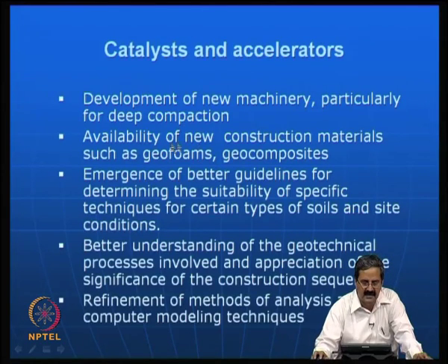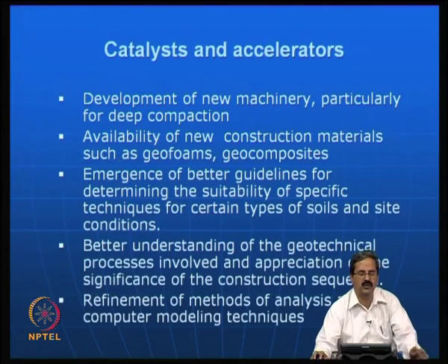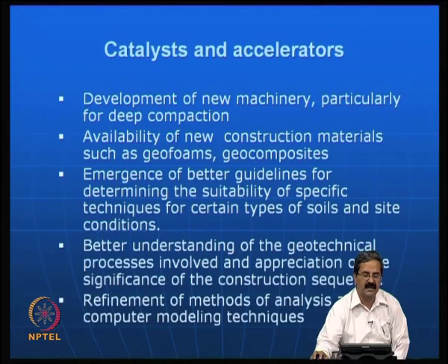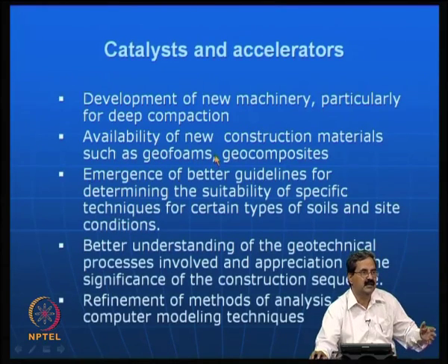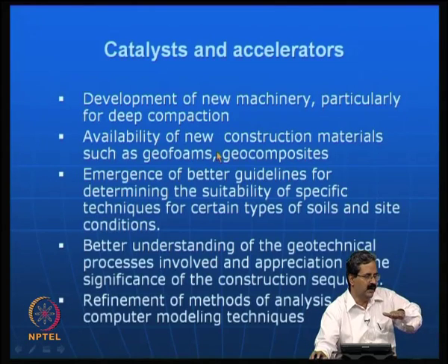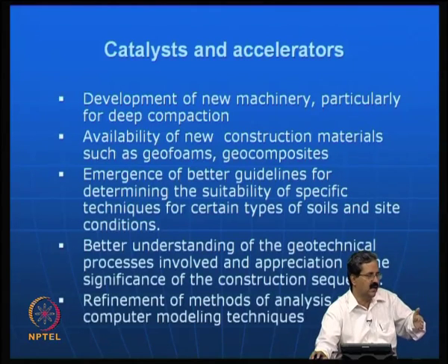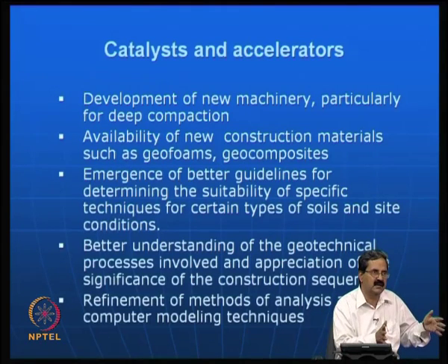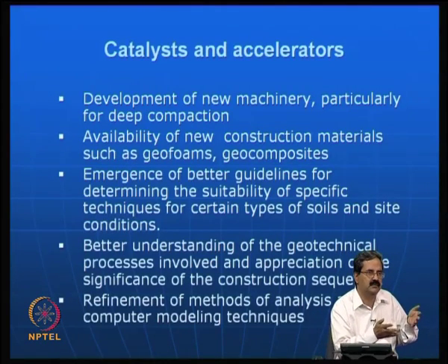So, another one is the availability of new construction materials. There are many actually, if you go to construction of roads and other places, there are so many materials that is amazing. For example, I will tell you the case of a geofoam, I will show you photos also. Normally in road construction, what do you do? You make a subgrade, subbase, base, and then wearing course, right. Then you see that half the road is cut, and you do not allow the traffic to go. It is always a standard scenario here, but geofoam is one material, you just bring it and place it. It has all the properties that you want from the subgrade.